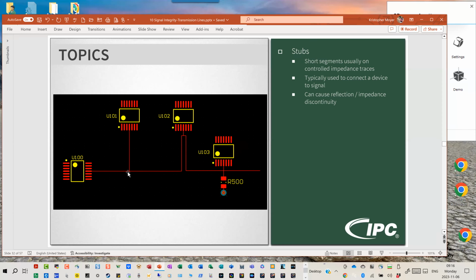So immediately in my digital signal, or in my transmission line, I will see an impedance discontinuity where I will see a change from 50 ohms to 25 ohms at this point. So I'll have a significant reflection or signal integrity issue here. Now, this is the worst case right here where I go completely long right here. This is a little bit better here where I try to route up and only have a small stub here, but I still have that issue here.